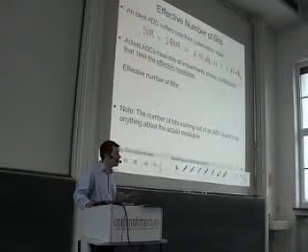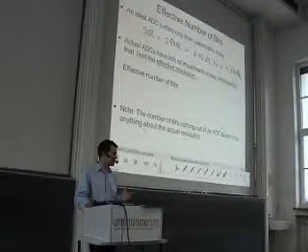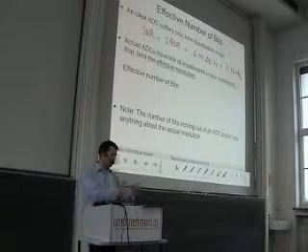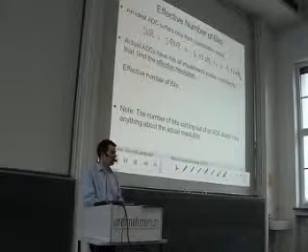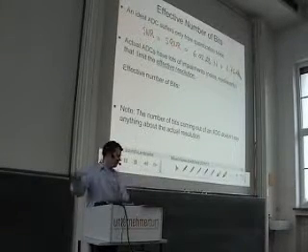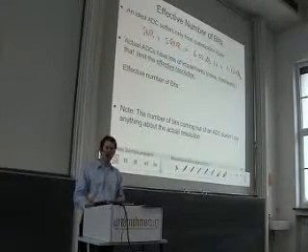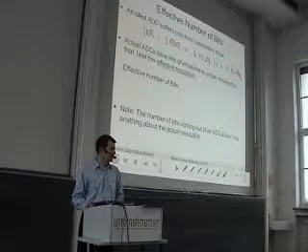Now we did it the other way around. We said, okay, there is no ideal ADC. In reality, we always have noise. And we have this dynamic measurement to compute the signal-to-noise ratio. We said, okay, we let this ADC running, we log all the data, we compute the spectrum, and from the spectrum, we compute the signal-to-noise ratio.